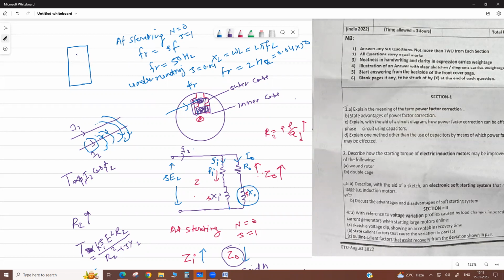In rotor the effective cross section area is reduced. Okay. Due to skin effect, resistance is increased. So at starting, rotor frequency is high, then skin effect is high, means resistance is high. Then it produces a high starting torque. But when running condition, the frequency is reduced, skin effect reduced, the rotor resistance is reduced, means impedance. Got it? The deep bar rotor also works in that case.